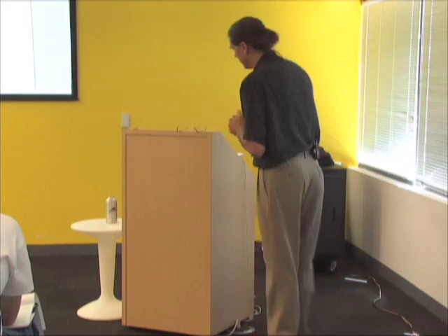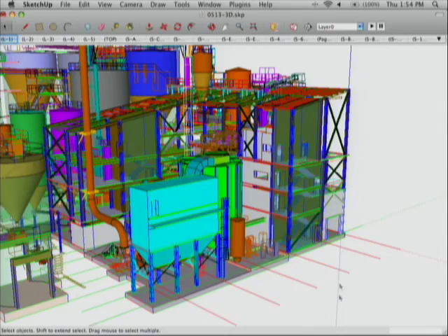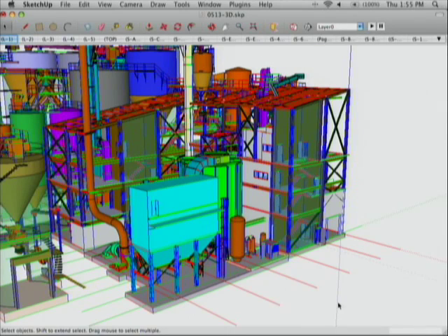Styles. I really like to have a style that tells me if I'm modeling orthographically. And I saw Aiden show this earlier in the day. There's a lot of red, blue, and green in this model because things go on the red, blue, and green axis. And it's a really major deal once you figure this out and you notice that a lot of stuff's black and you thought it was vertical. I mean, you thought it was on one of the axes. It makes modeling a lot simpler.